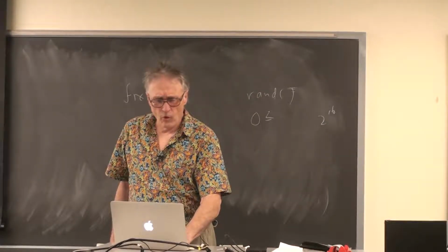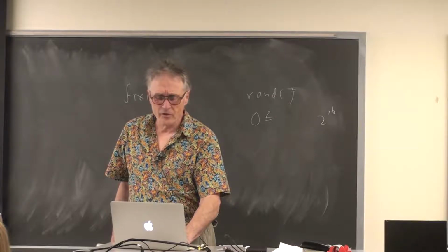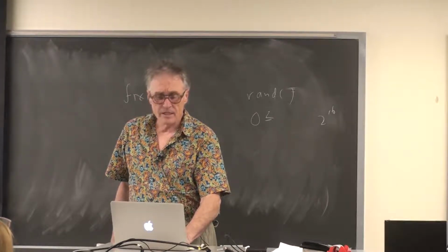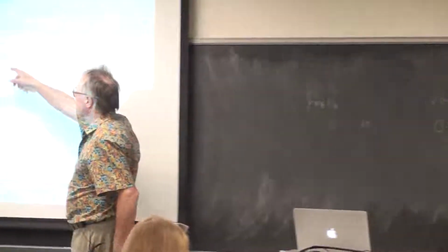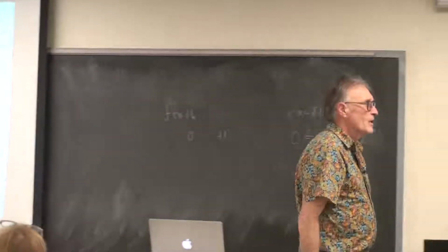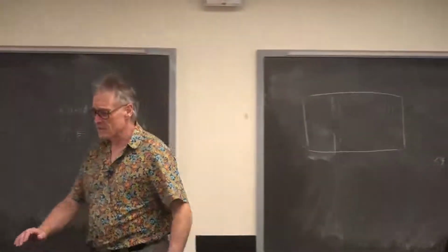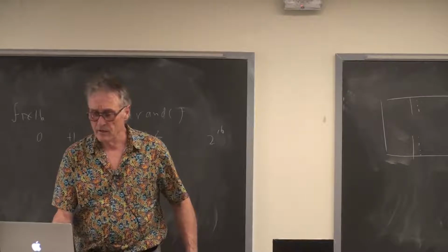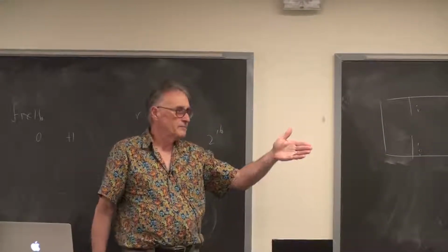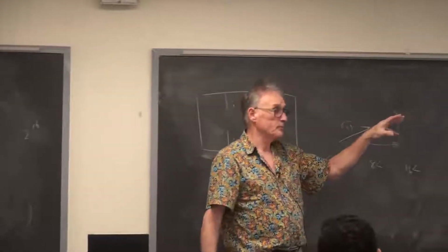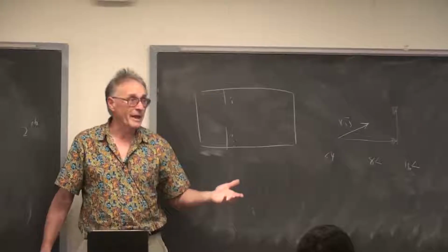And I think I said at one point, down in this VREF as a digital analog converter page, I wrote a wave file to header compactor that puts out a C header file as a static, constant, unsigned char. You'd probably want to change this to unsigned short. But you could, and this goes on for 7,000 entries. This is kind of a long, tedious, boring file. But who cares? MATLAB generated it. You can take that file, include it as a header file, and that array will be put into Flash for you. That could be your sound file. It could be any wave file.